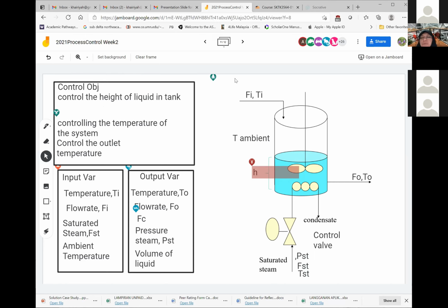Now, if you're told there's a pump at the flow in and it is set to be the same as flow out, then flow in can be equal to flow out. So in that case, you don't have to control the level. But nothing is said about flow in or flow out, and we don't know whether it's equal. So most likely it can vary. So of course, yes, H, the level, we need to control it because we do not want the tank to go dry or to overflow. Okay, so that is good.